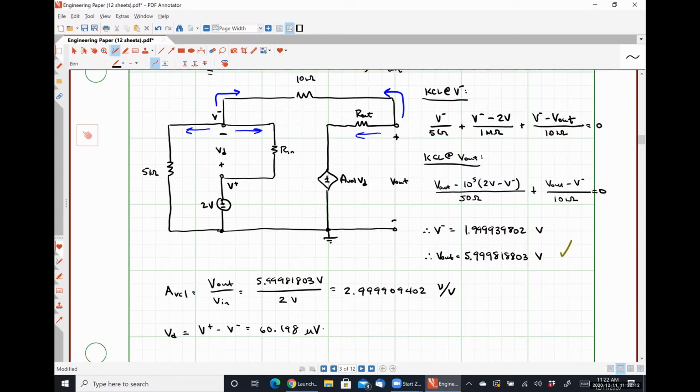Sure, that feedback resistor right there says this V out is not going to be the same as this, because there is current flowing through our output resistor, right? So we're seeing some small perturbation here because of our output resistance. Perfectly okay, just wanted you guys to be aware of it so that if you think, oh, I could check my answer this way, you kind of can't, all right? Just to be real clear.